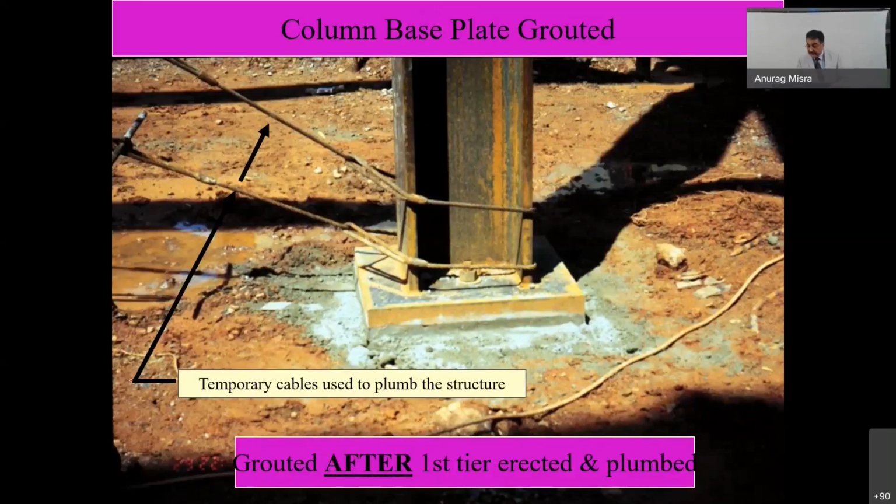If you have, this is the base plate, this is an I section, and you have a moment connection. So this is the top of the column. Your base plate is usually, these are the bolts coming out, and we do provide leveling nuts here. First the leveling nuts are done, and then your base plate for this column rests on those leveling nuts.